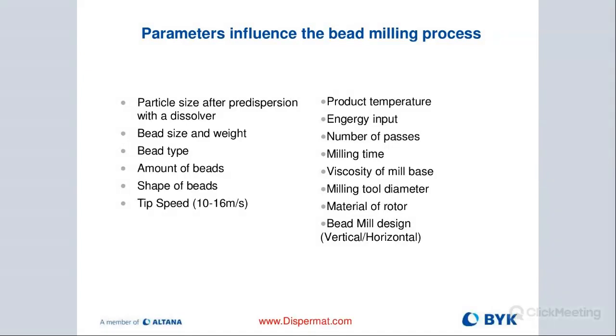Unfortunately, this is unavoidable if you're using stainless steel, as the media would hit the container walls or the milling chamber, and that will wear down that metal into tiny particles that carry over into your slurry.